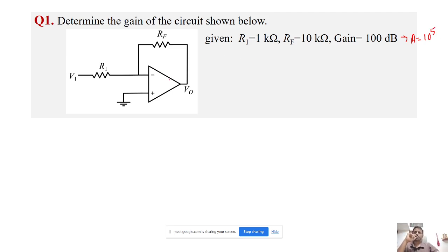As sir has mentioned, we will follow the same steps. Say V1 is the input voltage. Due to its non-ideality, though the non-inverting terminal is grounded, there will be some voltage difference at the inverting terminal, though it may not be V1, say V2. If it were an ideal op amp, whatever is the voltage here should be followed here, right?